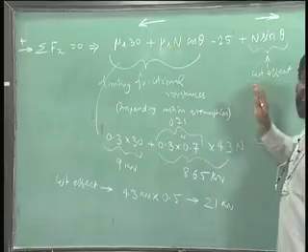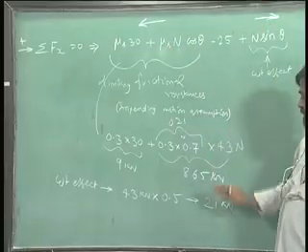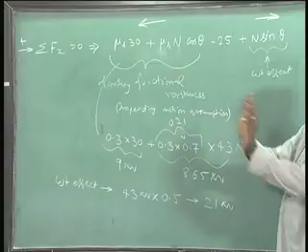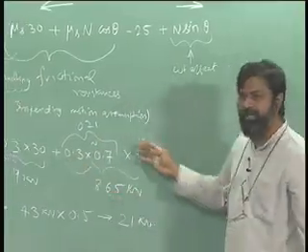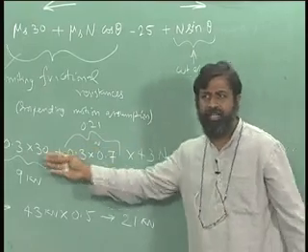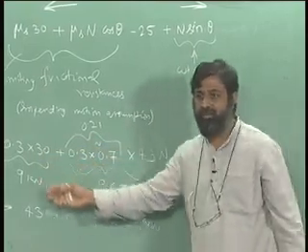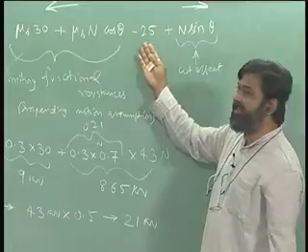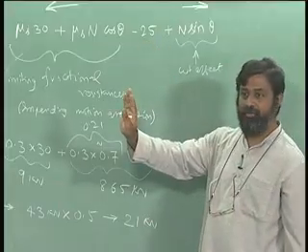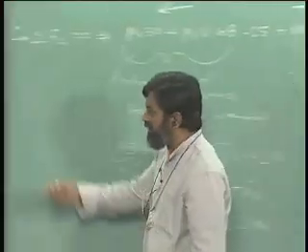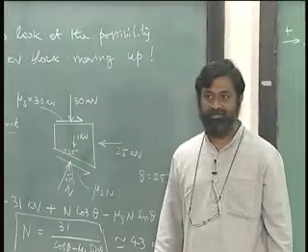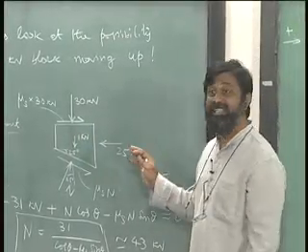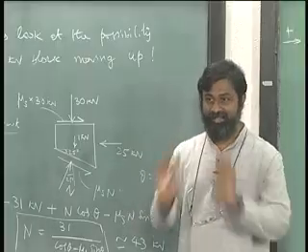This guy needs 21 kilonewtons approximately to keep it in place. Do I get that 21 kilonewtons from here? Roughly okay, 18 kilonewtons is what I am getting from here. The remaining I can supply through a force 25 kilonewton because it is opposing the motion towards the right hand direction, alright. So 25 is more than enough for me to keep it in place.